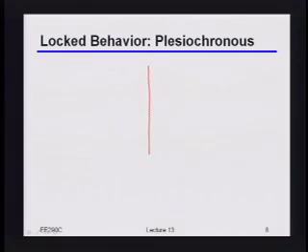So what I want to draw now is phase versus time. So first of all, I'm just going to draw in blue here. If I told you that I have a frequency offset, what does that translate into from the standpoint of phase versus time? And don't worry about wrapping and things like that. Just what's the shape of phase versus time if you have a frequency offset? Yeah, it's just a ramp, right? It's a straight line, okay?